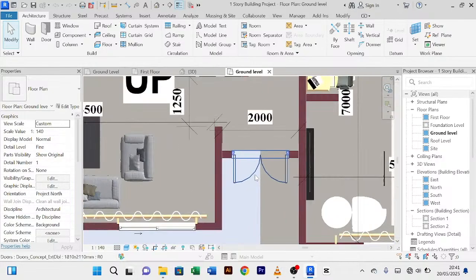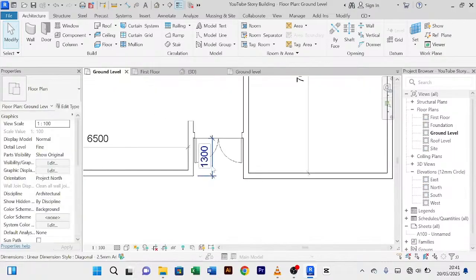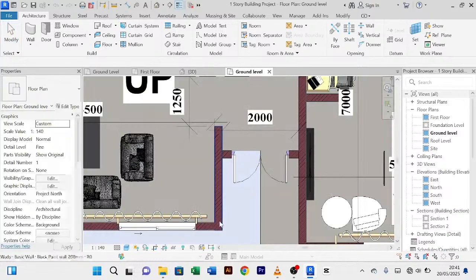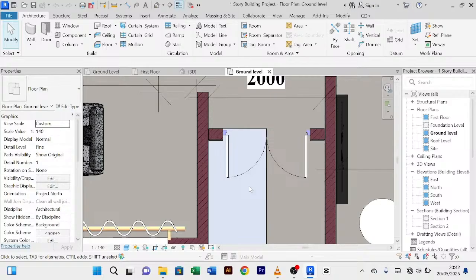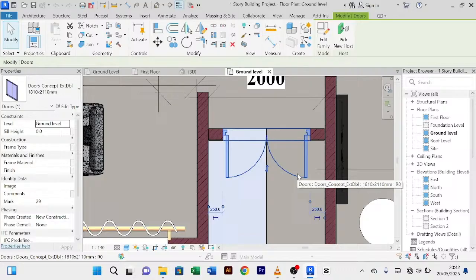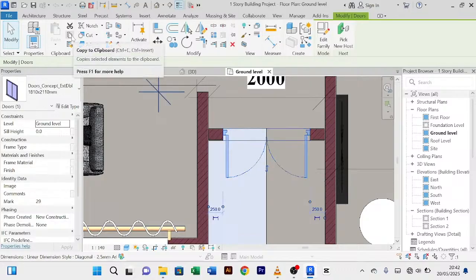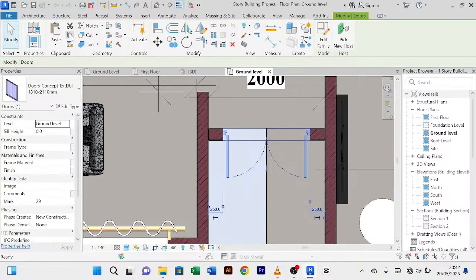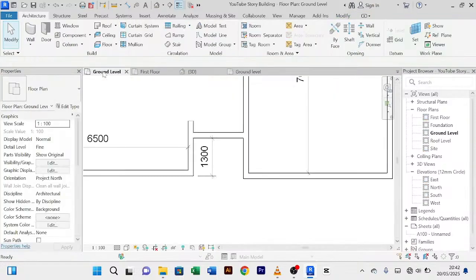We are going to use these doors instead of this one here. I really don't like this at all. So for me, what I'll do, and the same can also apply to you, if you have a project that has all these components, you open the project in Revit, you click on the component you want to copy, then you come to this tab that says copy to clipboard, you copy it, then you go to the browser or the level or the ground where you want to paste it.